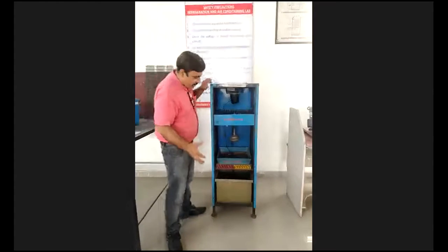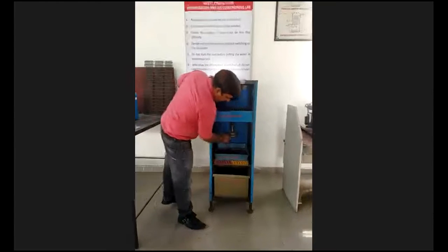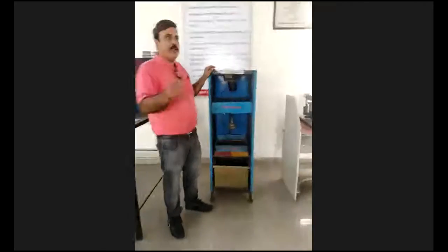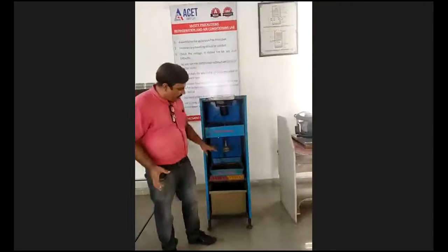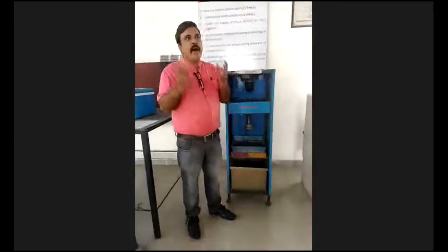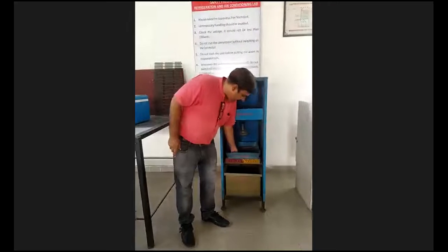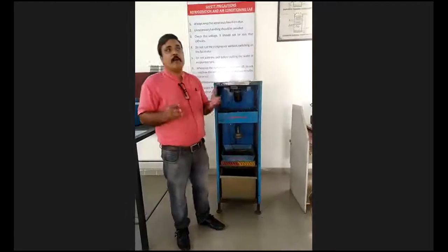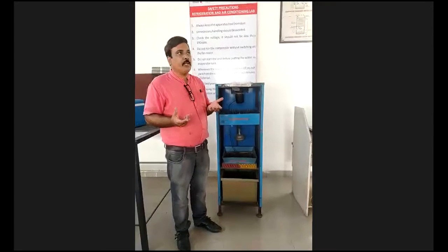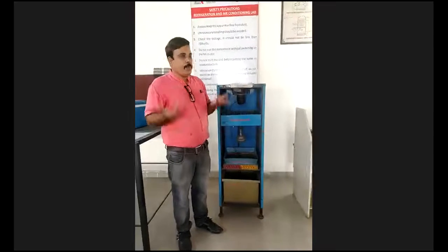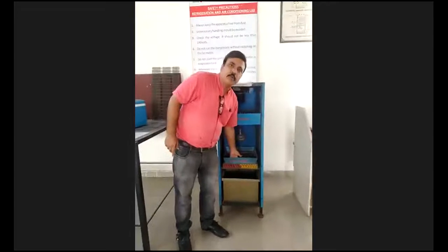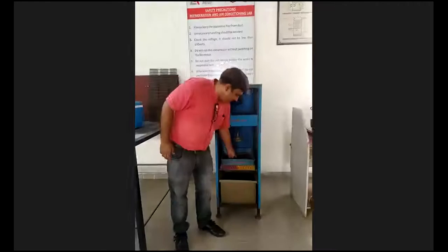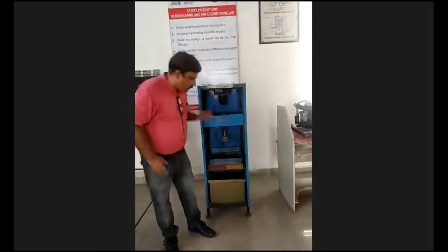When it is passing through this pipe, water is flowing over this pipe. When water is thrown in the form of mist, in the form of fine droplets, and comes into contact with this pipe, what will happen? It will get evaporated. When water gets evaporated, the remaining water will be cooled again, so it will produce more cooling over the pipe.